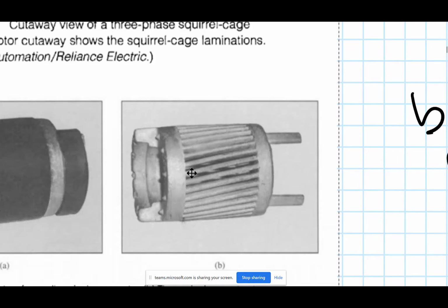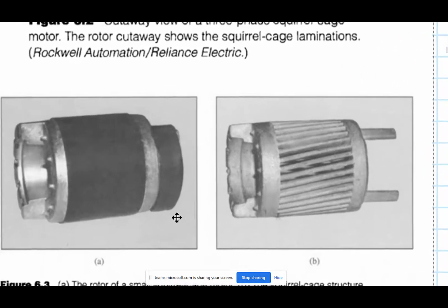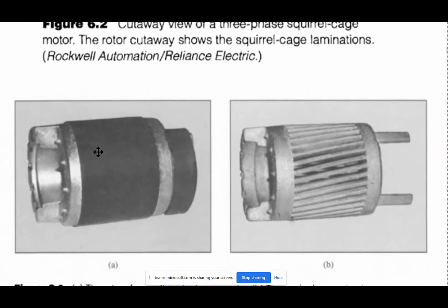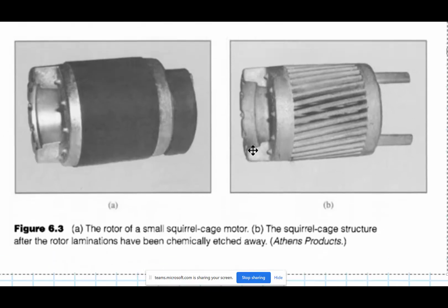And essentially what they do is they make the core material, and they treat it kind of like a casting, and then they pour the molten aluminum into it, and it fills it up, and now you've got a rotor. It's quite easy to do. I mean, very effective. These aren't straight bars, because the little skewing reduces the ripple and makes the motor turn in a smoother way.